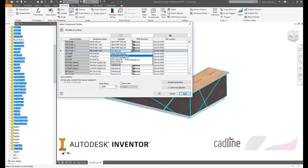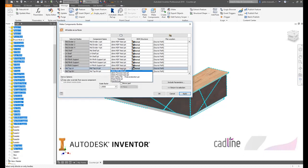and you might be thinking, oh, this is taking a long time, but obviously bear in mind, in the bottom up approach, you'd be taking twice as long, if not longer than this, because you'd need to put those parts together and then actually create the constraints, where with this approach there's no need for constraints. It grounds all the components but holds them all in place for you. So again, I've got two top panels at the bottom here, so again I'm going to use my 22mm ply nest. Once I'm happy, I can hit OK,